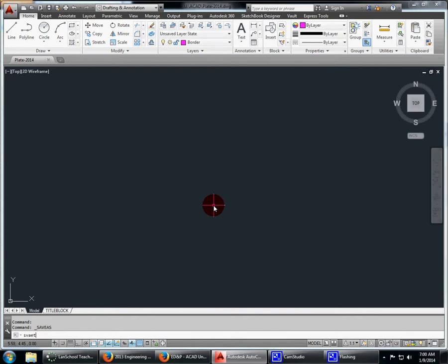I'm going to type in save time. You just type it in and put it in. And set your save time to every 10, or 5, or 15 minutes. What this will do is save it to your folder every 10 minutes. So if you open up a file, do a save as, save it where you want it to go, do a save time, it'll automatically save to that same file every 10 minutes for you. So just in case we lose electricity or something, it'll cover you.